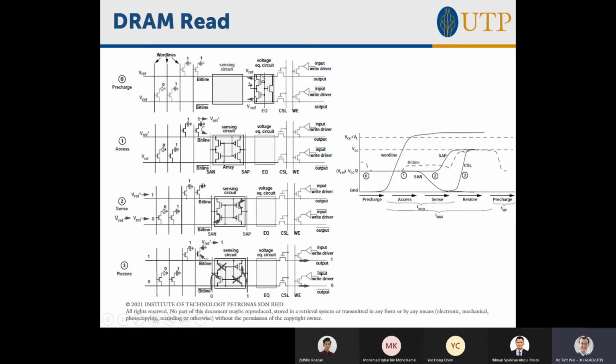And what is that voltage? Conventionally, the bit line is going to be VDD divided by 2. So if you're at a 1.8 volt process, both will be held at 0.9 volt. How is it usually done? There's going to be this equalize symbol here, and there's going to be VDD over 2 driving here. Then you just turn on this transistor, and it's going to force both lines to be the same. And you're also going to have this transistor here, also forcing them to be at the same voltage.